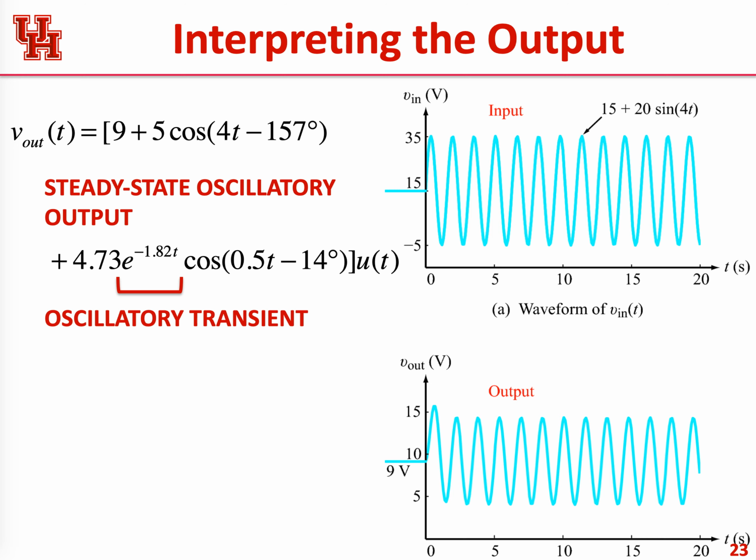So one part of that reliability has to do with taking care of the transients, right? In this case, the transient dies nicely and quickly. And the omega for this has nothing to do with the input, right? So this corresponds to the modes. These values are coming from the modes of the circuit rather than the forcing, which is the input,